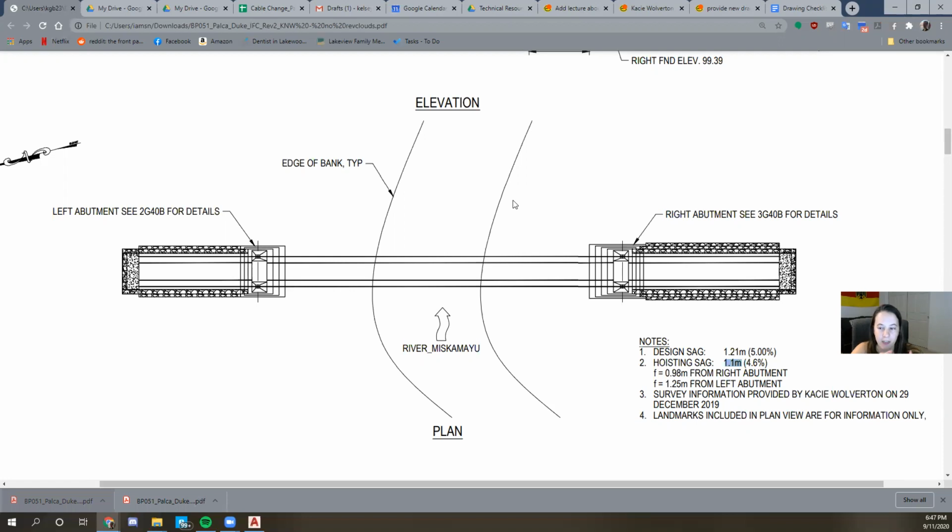Another aspect is that you'll need 0.98 meters for the walkway and the handrail cables, so you'll really need 2 spray painted lines. Then you can also have 4 spray painted lines, and you can find where that low point is on the higher tower, because depending on the topography of the site, you might have a better vantage point on one side. You want to make your eye point on the auto level level with the bottom of the cable.